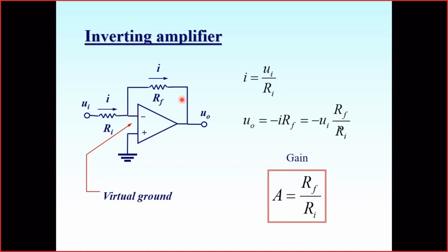There is also the temperature effect, the current which is produced in any resistance itself. It's so-called thermal noise, temperature-related noise. Actually, it's expressed as a chaotic current, which may change direction and amplitude and oscillates over the resistor RF. If our RF is high enough, this oscillating current causes quite a significant voltage oscillation in the output.